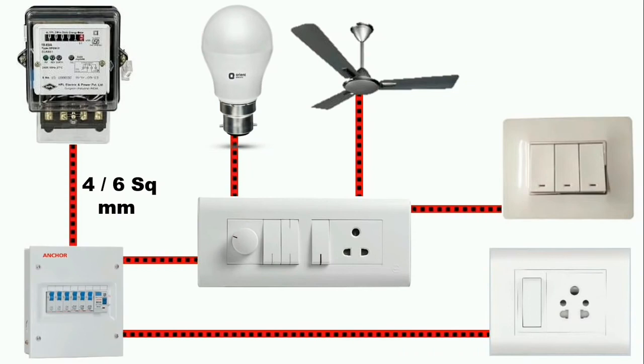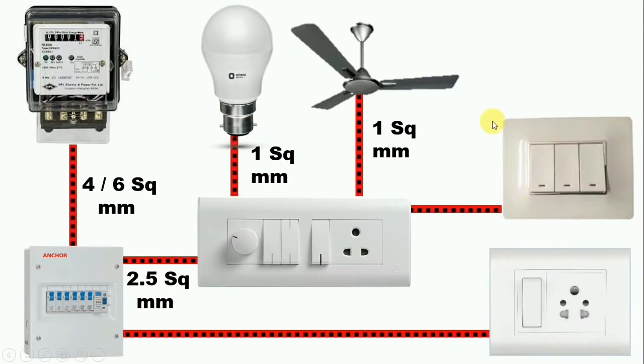Now, from your distribution board to a switchboard where you then distribute your lighting, or should I say a switch box, you want to use 2.5 mm. Now, this switchboard could also contain maybe a socket outlet. So if you use 2.5 mm, you see it caters for the socket outlet, because when you're using a switchboard, there will be not much time to make variations. For if you use 1.5 mm, then you are risking the socket outlet, there is a very likely possibility that they might burn. So from the switch port to the lighting points, you use 1.5 or 1 mm.